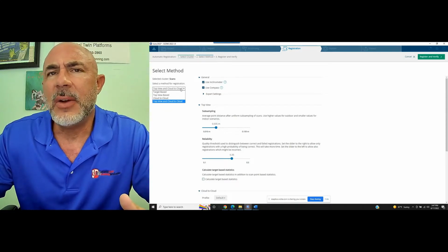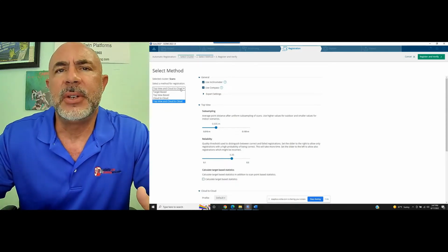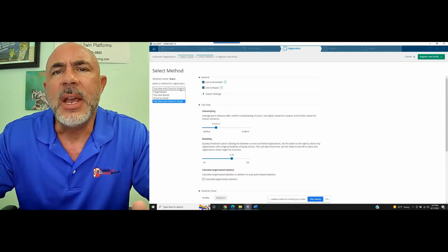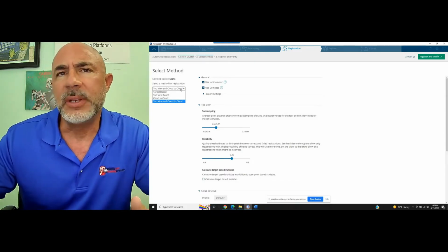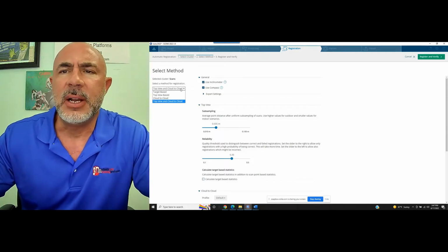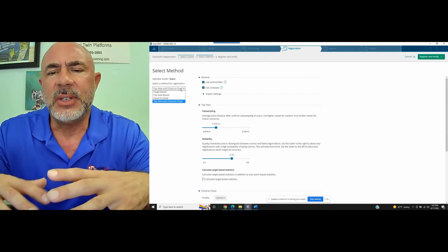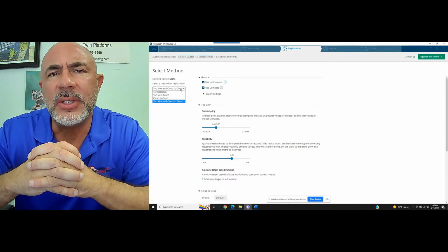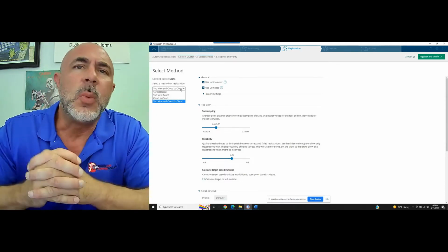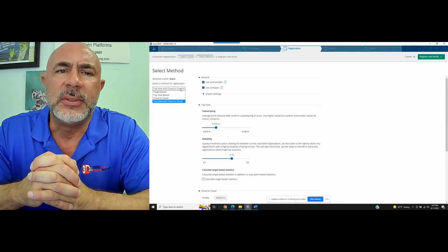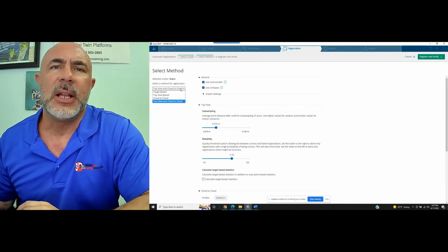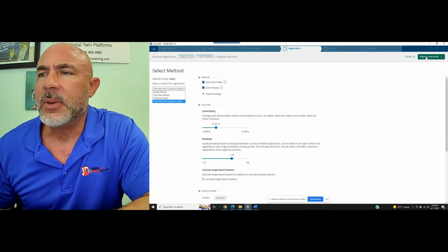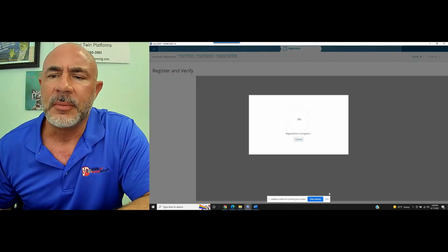And then cloud to cloud is the secondary method they're going to use. So once it's basically stuck together with top down, it's going to look for X, Y, Z points in space. And once it does this, it's going to sort of lock those scans together in an even tighter registration. So that's why they use a default of top view and cloud to cloud registration. As I said, everything else can stay the same for what we're doing, and then we're going to register and verify.